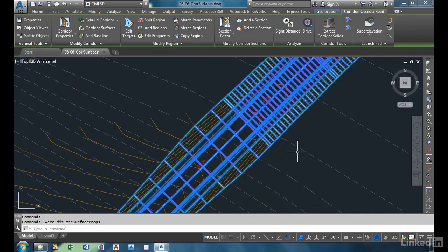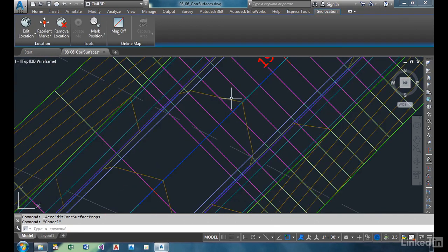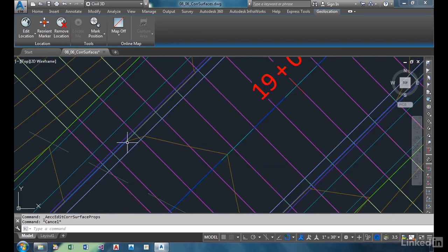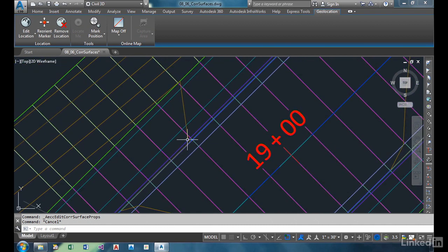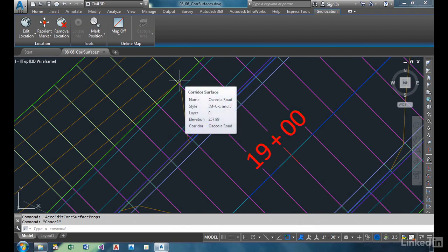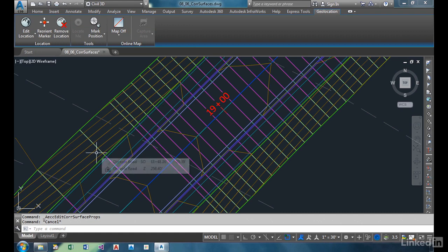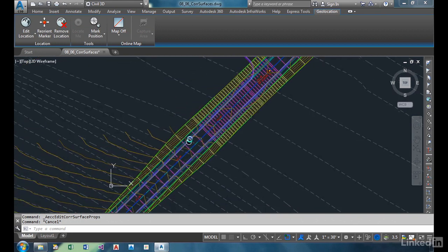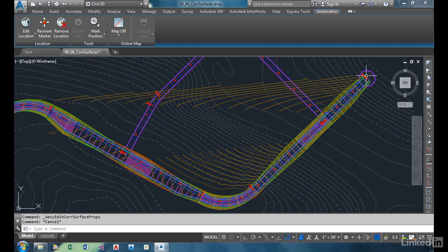And what kind of surface definition do we have? You see the crown of the road, it hits the edge of our gutter. The gutter is a little bit more of a greater slope than the road itself. And then we find that the contour runs along the actual curb, goes across the top of the curb, and then begins its 2% until it hits the edge of the sidewalk and then daylights in some form. So a very clean, well-defined surface, with one exception. We need a boundary. We have triangles going from all the way across here to all the way here. We need a clean boundary.